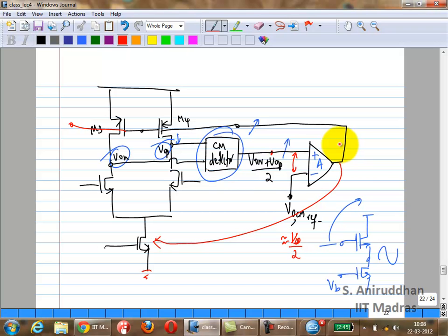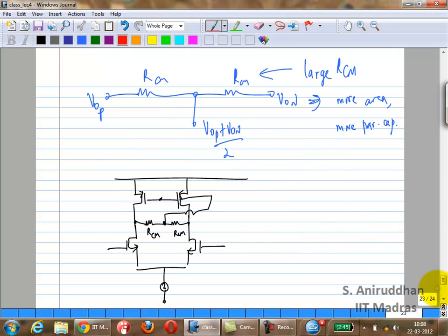So you connect it just like you would with the diode connected case, except you connect it through resistors on both sides. So the output is biased at VDD minus VSG3/4. So the output bias is decent, somewhat well defined. Maybe not at the point where you want, but it's well defined.